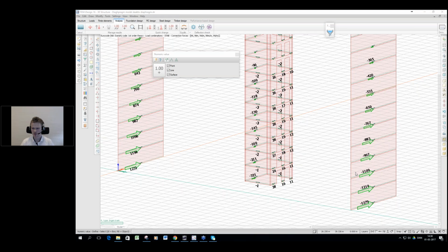Related to the Eurocode 2, Labib says, so in prefab and according to Eurocode 2, we can't refer to slabs as stiff. I don't know if it's the Danish national annex, but we can distribute like that here in Denmark. I'm not sure if it's because the Eurocode we use is a combination of the Danish national annex and the normal Eurocode, and it's okay here to transport the forces like this.